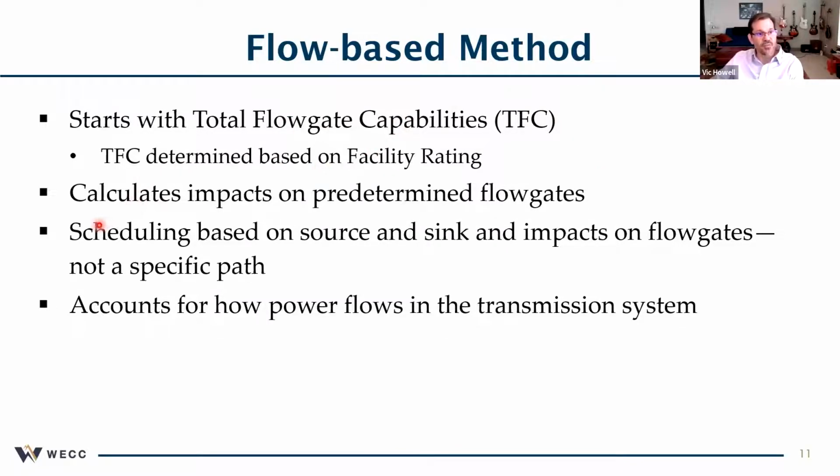And then the process calculates the impact on those flow gates. So as we've talked about, scheduling is based on a source and sink approach, and it looks at impacts on those flow gates and doesn't look at a specific path. And the flow-based methodology also accounts for how power actually flows in the transmission system.